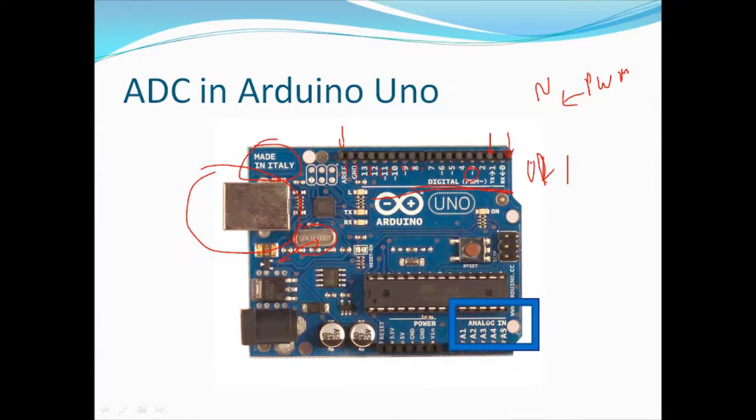Next, there are a lot of ICs, and there is something called L, and also TX and RX. TX stands for transmission, RX stands for receiving. When this turns on, it flashes, and this is the light on the default pin. I think the default pin is 13 or 12, I'm not sure which, but by default, if you want to check whether transmission is working, this is one default pin. And here there is a reset button.